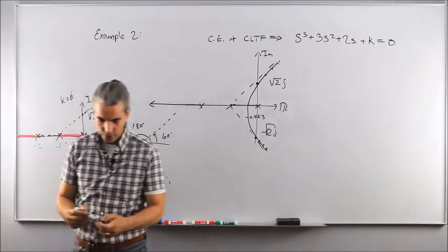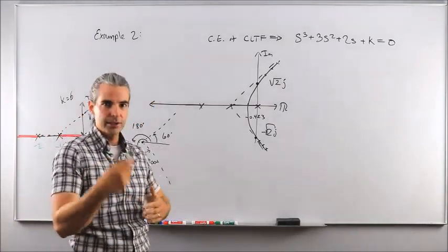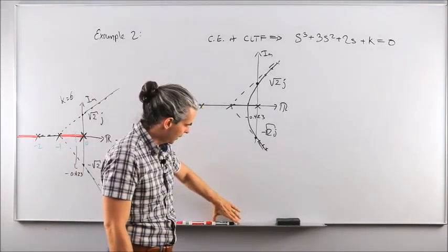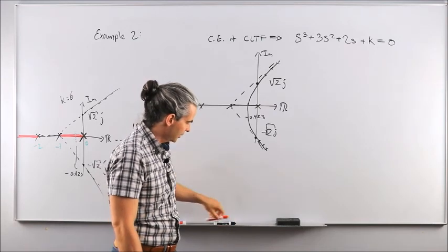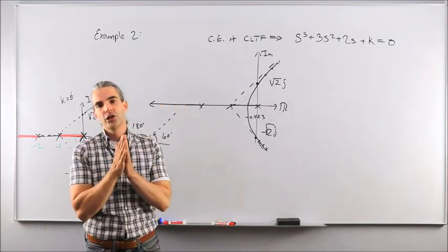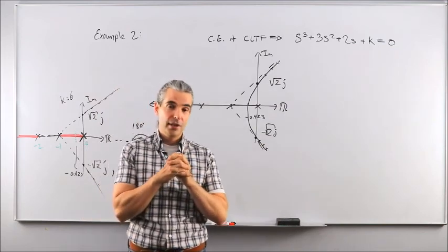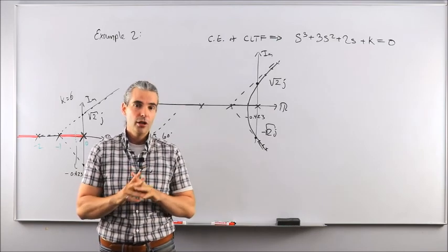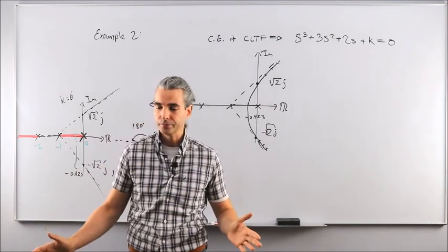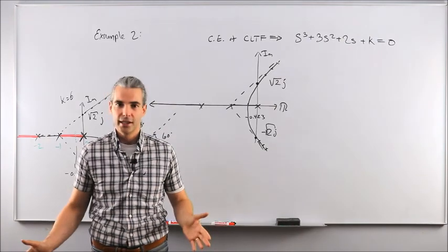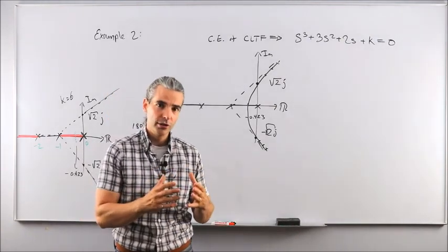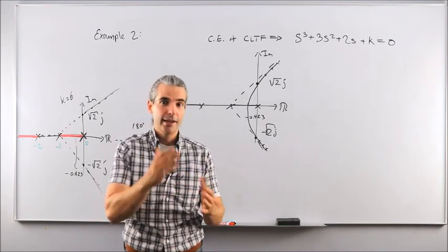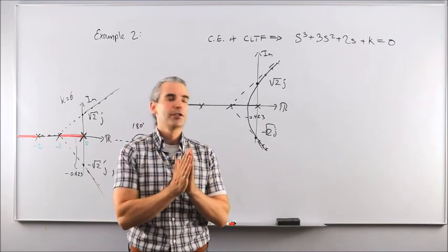It's, again, just a simple step-by-step procedure. Think of it as a recipe. You are cooking a root locus out of the main ingredient, which is your open loop transfer function, and I cannot stress that enough. If you were to begin the process with the closed loop transfer function, the whole thing would not make sense in the end. So start the root locus construction, or cooking, because this is a recipe, from the right ingredient. And that ingredient is the open loop transfer function.